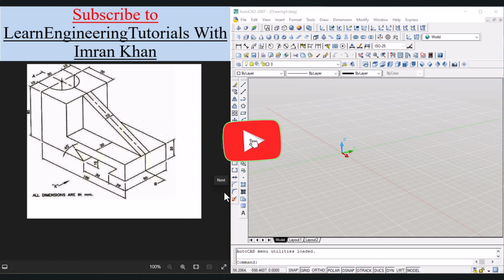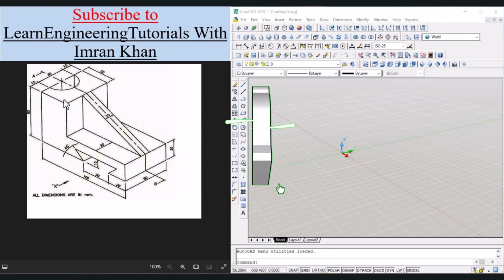Hi viewers, so today we are going to draw this object. The dimensions are given in this diagram. This X shows that this is the front view, this B side is the right side view, and the top view we all know, this is the top view. Here we can see a 60 mm because the dimensions are in mm. The length is 100 mm, width is 50 mm, and the height is 60 mm in total.